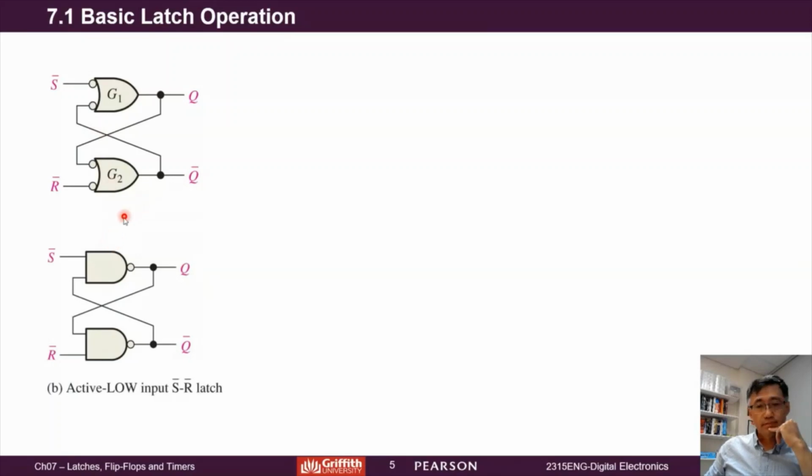Should be the same. Okay. So actually, we already introduced this in previous chapters. This is a NAND gate, right? We can change a NAND gate to an OR gate. Just push the bubble to the inputs, okay, and change the AND to OR. Okay, this bubble pushes there. We have two bubbles there, and then it becomes an OR gate.